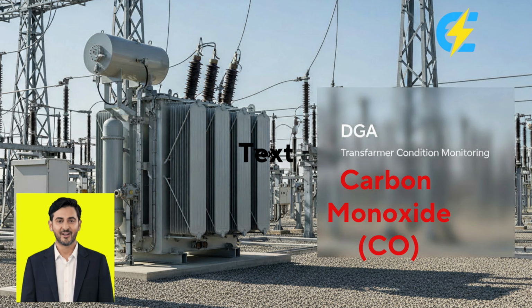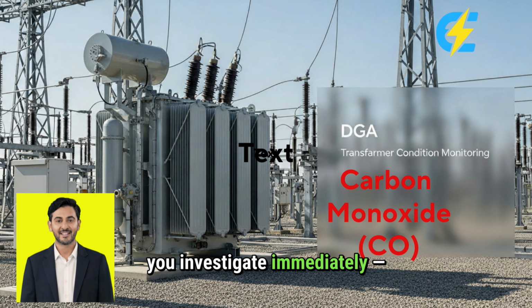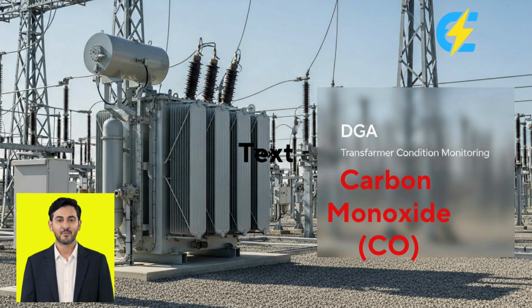Remember this rule forever. Hydrocarbons: fault energy. Carbon monoxide: insulation health. When CO rises slowly, you monitor and manage loading. When CO rises rapidly, you investigate immediately, because paper damage cannot be reversed.